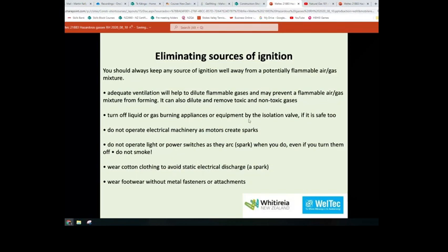Obviously, if you're doing drain laying or plumbing and you're digging a hole in the ground, you want to try and minimize creating sparks. Certainly if you think you've hit a gas main or you're smelling a gaseous smell, you need to treat it as if there could potentially be gas there that may be explosive, and also take care not to create ignition sources. You may need to create enough ventilation to disperse the gas that's there to make it safe to work again.